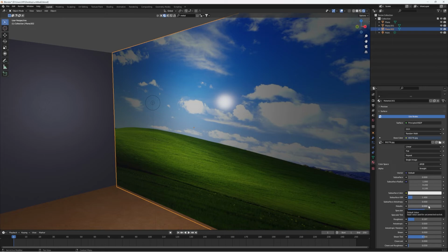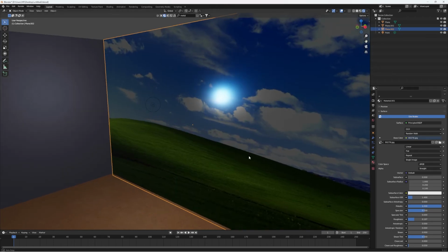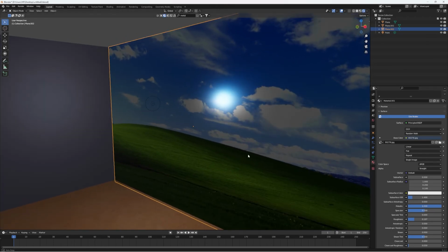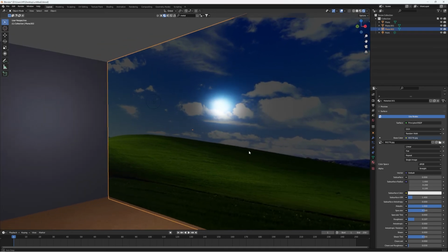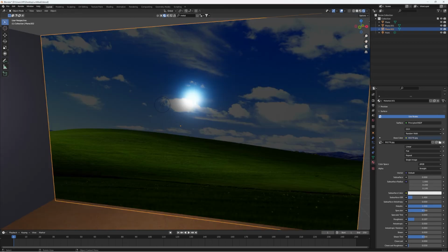Another thing that you may want to consider is the metalness, in this case the metallic setting here, which determines whether something is made out of metal or not. So 0 meaning that it's not made of metal, so it could be something like wood or plastic. But if you increase the metalness, you'll see that the surface becomes somewhat closer to a metal. You can actually see the quality of reflection become somewhat different now. Okay, it looks more metal-like. So these are the 3 other settings that you may consider changing when you are creating your textured material.